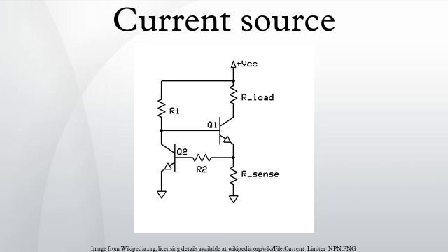Voltage regulator current sources. The general negative feedback arrangement can be implemented by an IC voltage regulator. As with the bare emitter follower and the precise op-amp follower above, it keeps up a constant voltage drop across a constant resistor. So, a constant current flows through the resistor and the load. The LED is on when the voltage across the load exceeds 1.8 V. The grounded load is an important advantage of this solution.